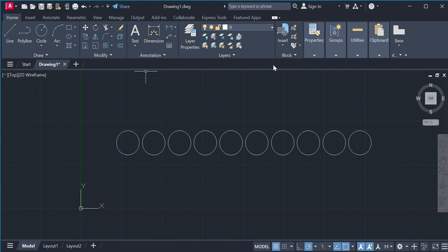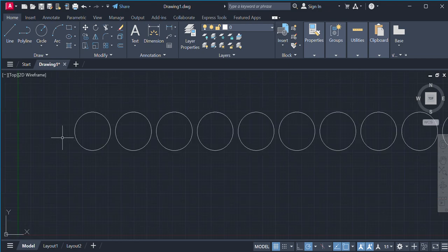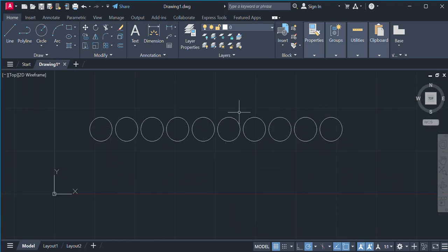If you open a brand new drawing, which says Drawing1 up there, it has no specified layers. The only layer it has is layer 0. So the very first thing you want to do once you get to a new drawing is to specify your layers and layer properties. This is to make sure that you're able to distinguish between the different things you're doing in your drawing, and that once you start printing, your work is visible and shows on the drawing in the way that you want.